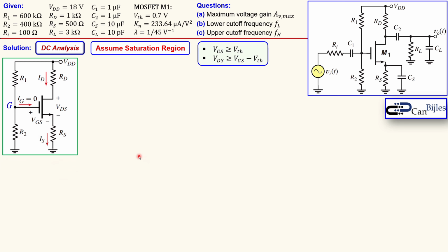Okay, this is now our DC circuit, because the capacitors will be open, so you lose those parts and have only the middle part, which is shown here. I also labeled the G, the gate node, the drain current, the source current, and the gate current. The gate current is 0 because this is functioning as a capacitor; for DC, it is open. You see the VGS and VDS.